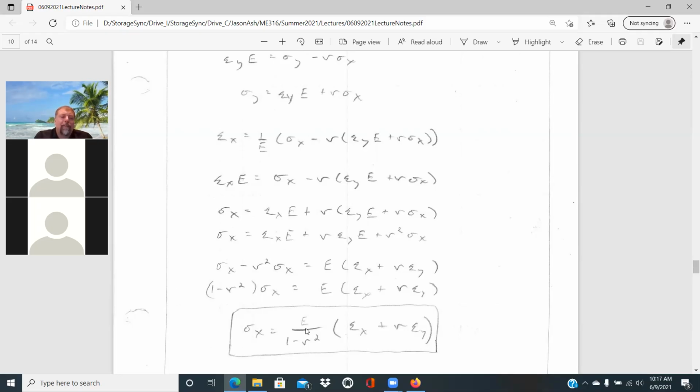They probably discussed that too in ME 216. Typically what you're doing is measuring, say, surface strains, for example, with rosettes. And so these values, strain in the X and strain in the Y, would be values that you would be measuring for a plane stress condition that's being applied. And then with that, you can solve then the corresponding sigma X value.